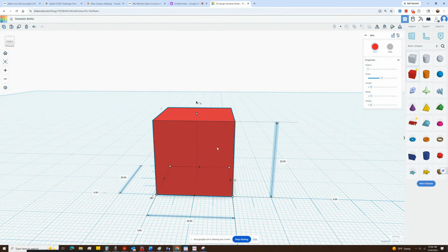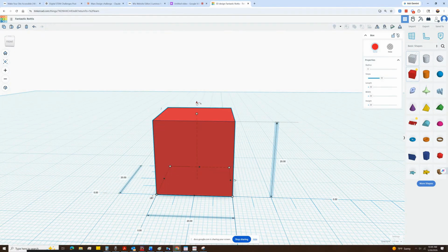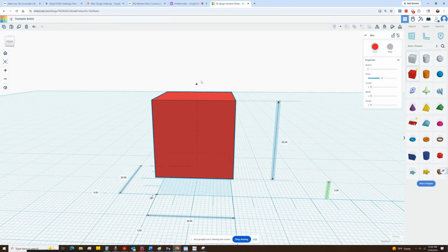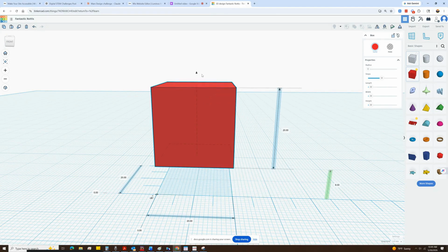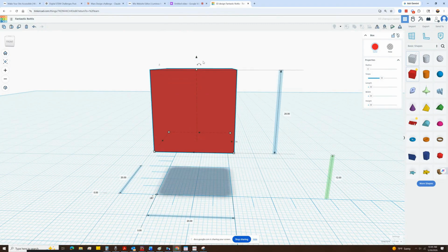All right. So now that we have seen how we can manipulate the object's size and dimensions, the next thing we want to consider is how to move the object in the z direction up and down. For this, you have this conical arrow over here. We can see this cone. If you click on this cone, hold it, you can move the object up in the air or down at the bottom. And the way you know it's moving is when you move it and you release your mouse, you will see a shadow. That way you know it's up in the air.